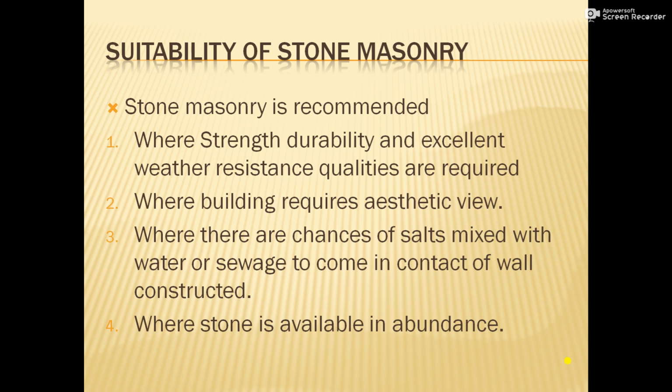Next, where there are chances of salts mixed with water or sewage coming in contact with the wall constructed. In the construction of sewers and water supply lines, the masonry comes in contact with salted water, and this also happens in some chemical industries. For that purpose we recommend stone masonry, as stones have excellent weather resistance as well as proper resistance against these properties.